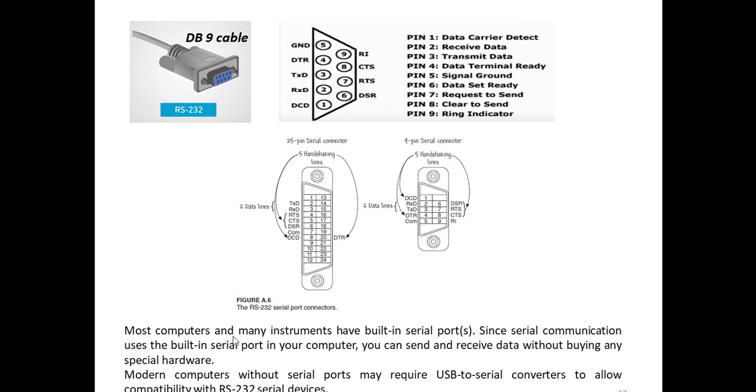So most computers and many instruments have built-in serial ports. Since serial communication uses the built-in serial port in your computer, you can send and receive data without buying any special hardware. However, modern computers without serial ports may require a USB to serial converter to allow compatibility with RS-232 serial devices. So let me